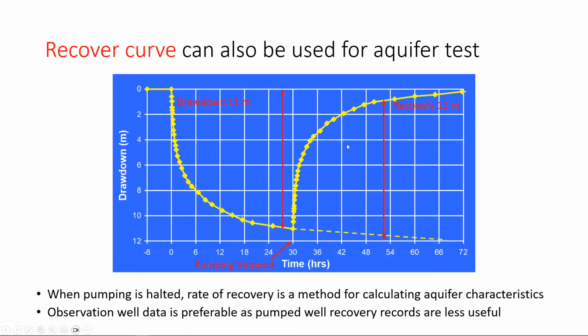Another thing, just to conclude the pumping test: when you conduct a pumping test, what are you observing? You are observing drawdown with time. So you're pumping the water out, and as you are pumping the water out, you'll draw down. So this is the time. Your drawdown will increase with time. But once you stop pumping, what will happen? You will start to recover. So your water level will start to recover.